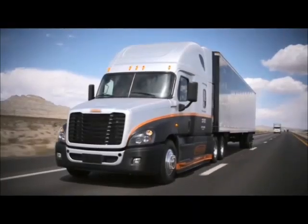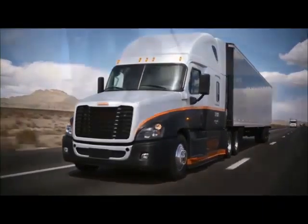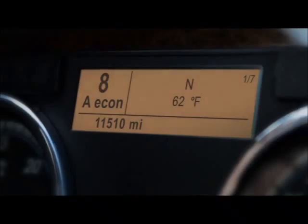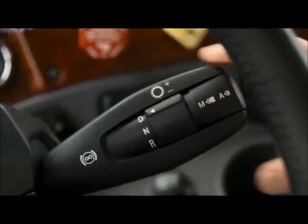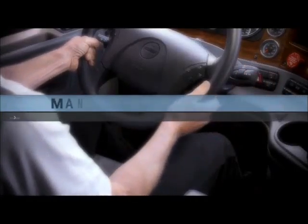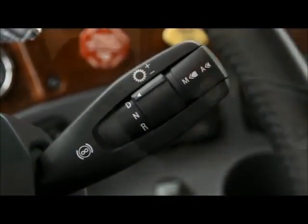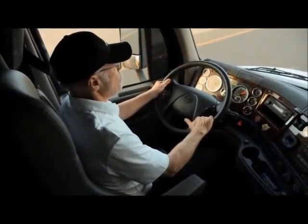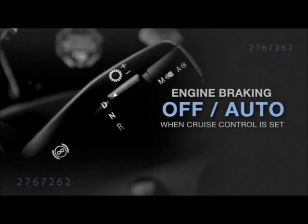Once the vehicle has achieved the set overrun limit, engine braking will slow the vehicle to stay within the set limits. The engine brakes may also force a downshift of the transmission to improve engine braking performance. Manual engine braking with the shifter stalk will always override the CC band switch. If manual engine braking is used, cruise control will be canceled and engine braking will slow the vehicle down. When the shifter stalk is returned to the auto position, cruise control will auto-resume to your cruise set speed.